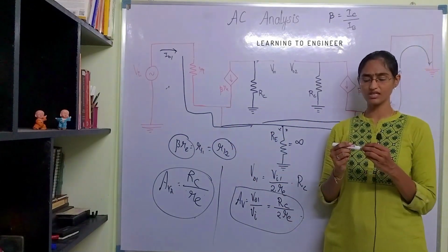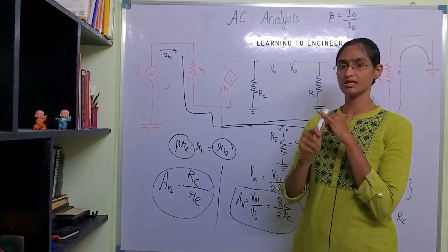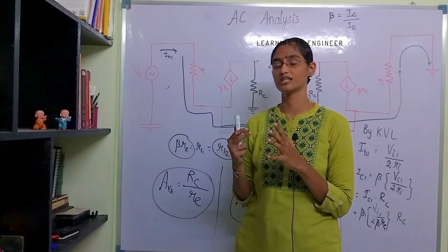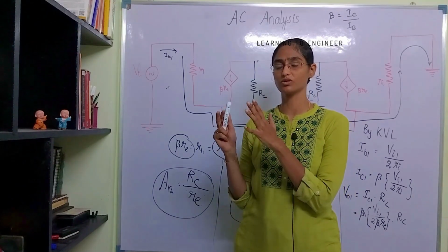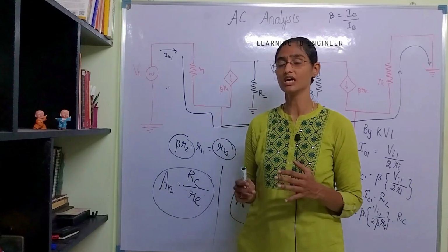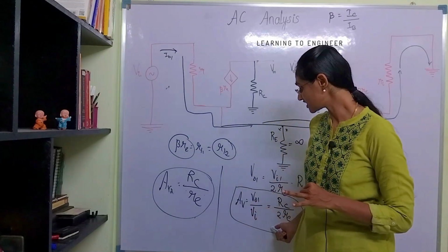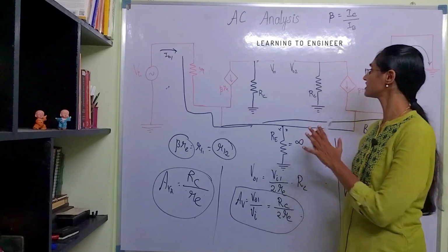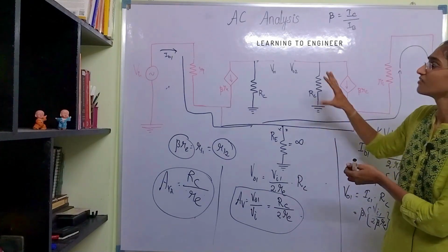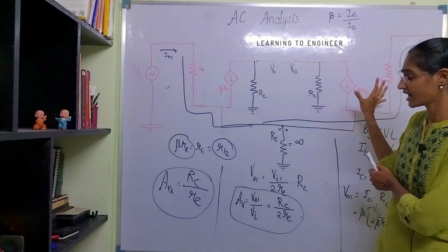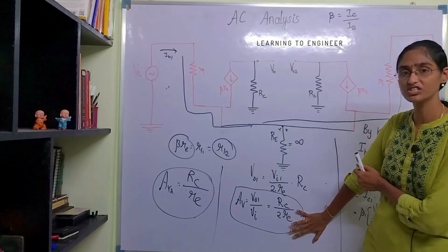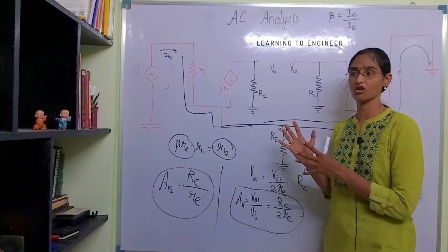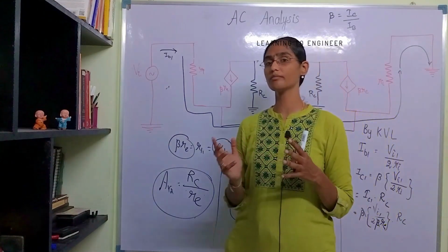So now we have seen three things. We saw the DC analysis part, where we saw only the operation of the difference amplifier because of the operating voltage plus VCC and minus VEE. Now we saw the differential gain, which means there is a differential input and output. Consider that this is 0 volt, okay. So we have applied differential input and we have considered the differential output. So this is the differential gain of this op-amp. How to find out the common mode gain?